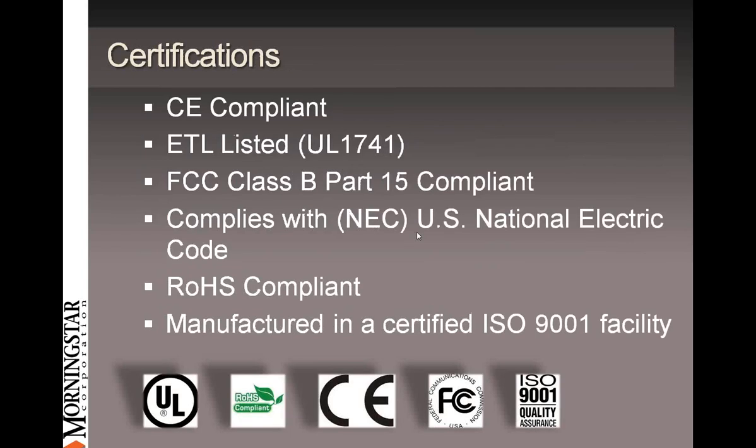Now, to talk about certifications, this controller is highly certified. We have CE compliancy, of course, the European standard for noise and radiated emissions. We are listed by ETL to meet both UL 1741 as well as the CSA Canadian standard, CSA 22.2. We meet FCC Class B. That's a very strict standard as far as noise goes, and we've already gotten some good feedback from some of our friends in the telecom industry that say it's quite quiet.